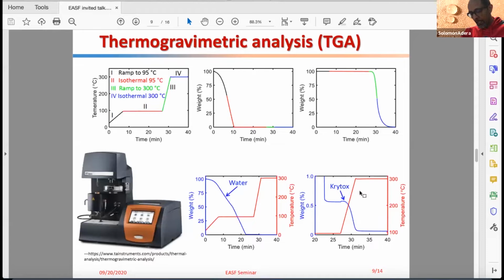The next thing we did, now that we know the identity of the satellite droplet is water, and we saw that the wetting ridge rearranged itself after the droplet departed, was to measure the rate of oil depletion: how much oil is depleted when these droplets fall. As I mentioned in the motivation section, one of the challenges with this slip system is that when droplets erode the oil, the performance degrades. So that's a major concern. We're interested to know how much oil we're depleting with these falling droplets.